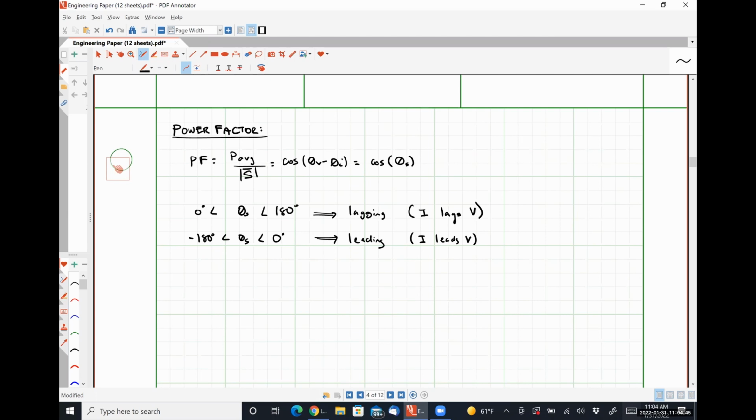And as a distributor, what the electric utility creates is the apparent power, the magnitude of S, right? So if the ratio of what we're absorbing and paying for compared to the apparent power is too low, we get fined because we are introducing an inefficient system to the grid, okay?